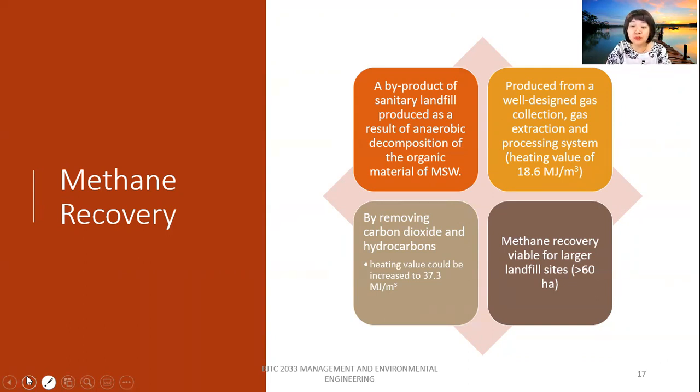It is produced from a well-designed gas collection, extraction and processing system. By removing the carbon dioxide and hydrocarbons, the heating value can increase up to 37.3 megajoule per meter cube. And the methane recovery is suitable for the largest landfill sites, which are more than 60 hectares.